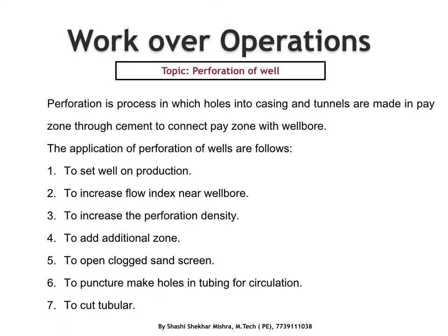Then it is also used for making holes in the tubing for circulation. Suppose we are not able to open the SSD and we want to kill the well for circulation or for acid treatment or any other thing. In that case we make a hole in the tubing to achieve that objective. And it is also used for making a cut in the tubular, like a power cutter.